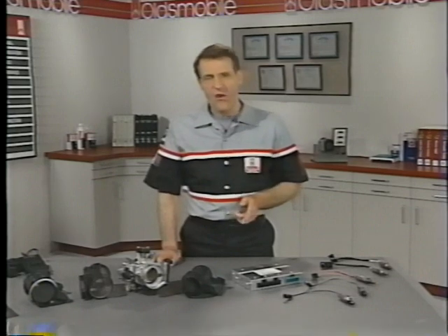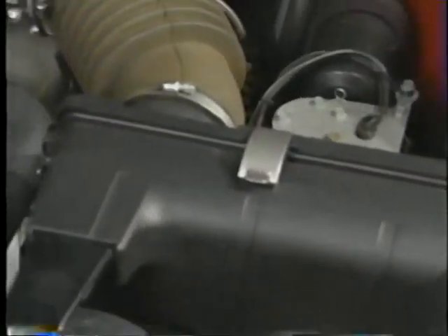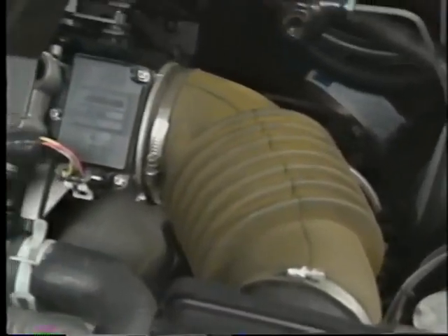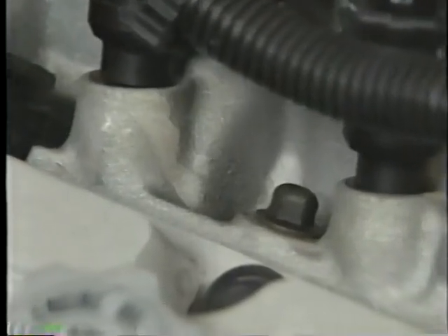To control the air-fuel mixture, an ECM or PCM has to know how much air flows into each cylinder during the intake stroke. This can't be measured directly, but it can be computed using a mass airflow or MAF sensor. A MAF sensor measures how much air moves through the intake manifold. The controller can use that information to estimate how much air enters the cylinders for each combustion cycle.